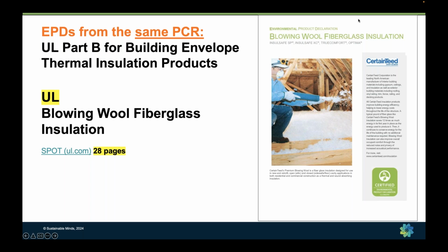And what's important to know about this particular EPD is that they're reporting 4 different products, you can see here, and they've reported them as multi-product weighted averages, which means that, you can do this as an alternative to a product-specific and plant-specific EPD, if all of these products are manufactured at pretty much all the same plants with different quantities of ingredients, ISO 14025 allows you to average results from different products, different plants, and report it as a multi-product weighted average, calling out highs and lows and with some other guidance around it.